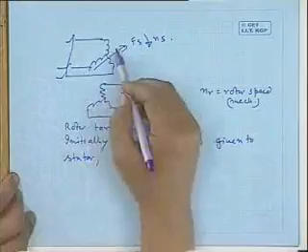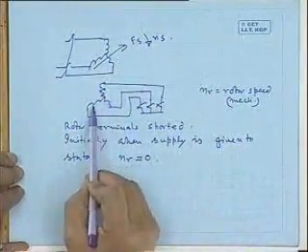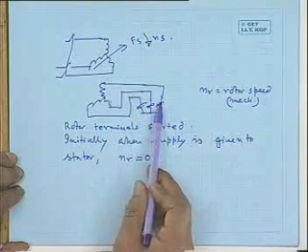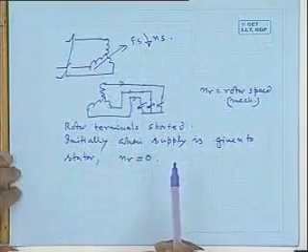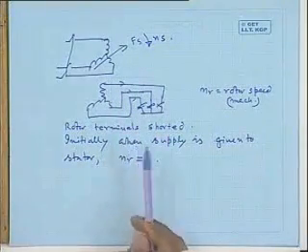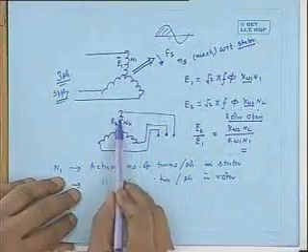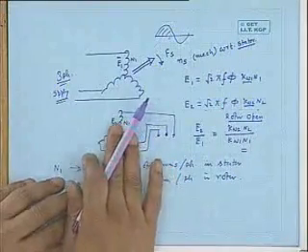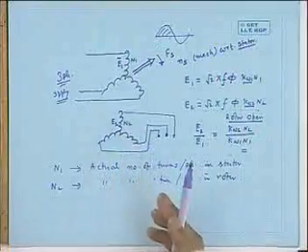Now, what is going to happen at t equal to 0 plus? You switch on the supply. A rotating field will develop. It will induce voltage here. But now the rotor terminals are closed. Therefore, there will be some currents here. Three-phase currents will be flowing. Now, with these rotor conductors, if you compare with the previous case, they were not carrying current, and were placed in a magnetic field.